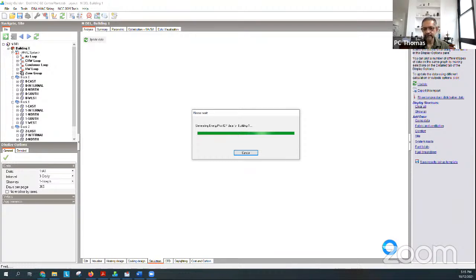And I suggest that when you start using DesignBuilder, you save the model before you make a big change. Then you can, if you want, do a save as a different model, make those big changes, test it out at every step to make sure it's working, so that if you make a mistake and something goes wrong, you can step back one step and go forward from there.